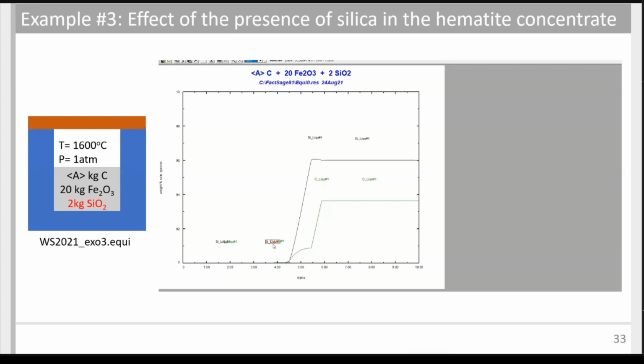We can also select the labels and remove some of them because now they're not presented properly. And what we see here is the evolution of the silicon amount and carbon amount. Any further addition above this threshold value of about 4.5 will lead to a transfer of silicon inside our metallic solution. And this is what we kind of predicted from the reaction module.